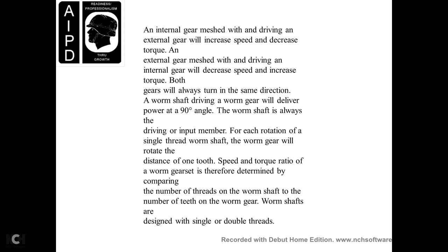An internal gear driving an external gear increases the speed and decreases the torque. An external gear driving an internal gear decreases the speed and increases the torque, but the gears will always be driven in the same direction.